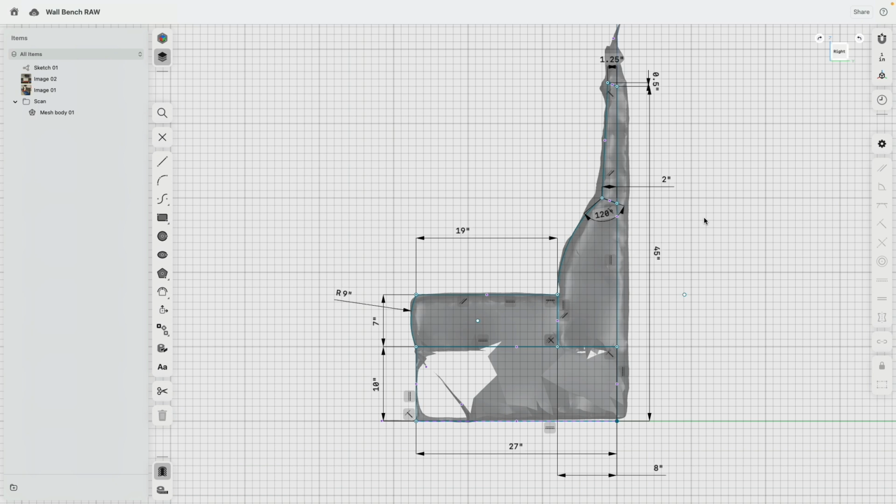So you see, with these sketch engines, you can work very precisely and very clean. And the nice thing is you don't have to redraw your sketch or your design. You simply adjust values. So for example, this point I would like to bring over a little bit. So here I say 19.5, but that moves this point over.